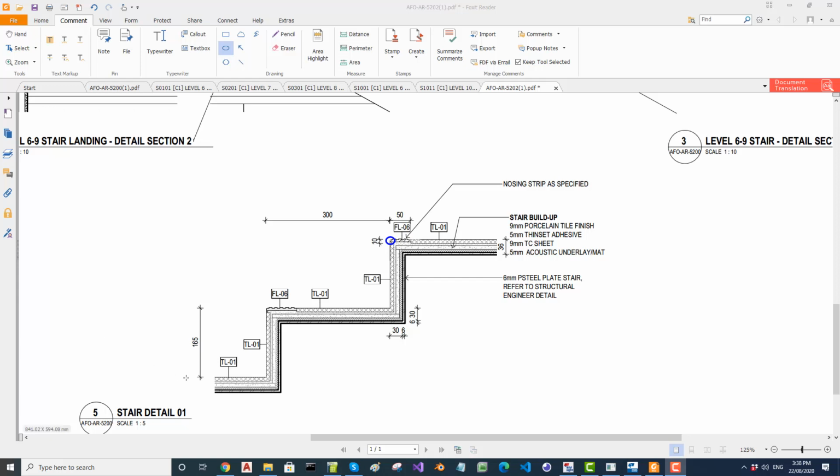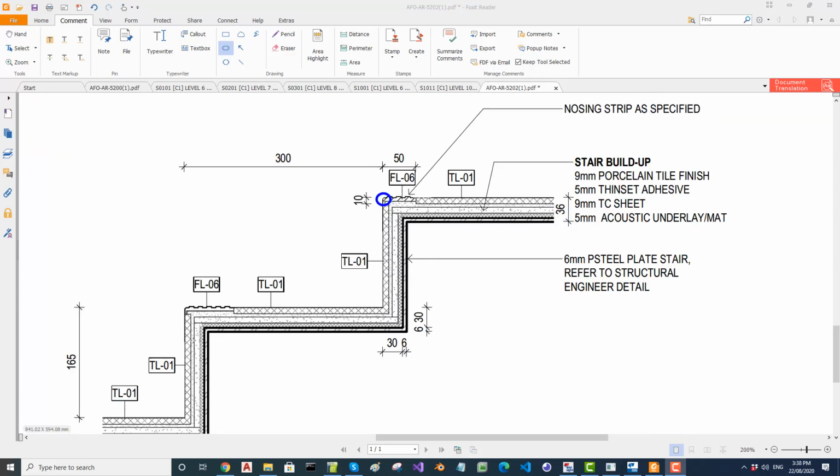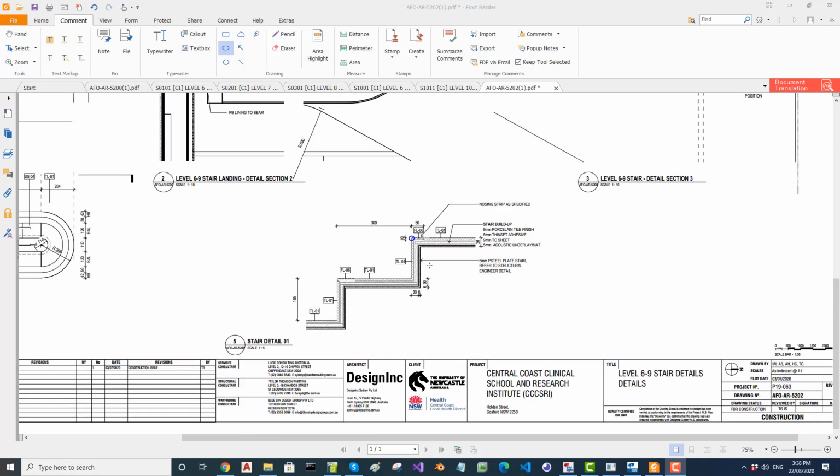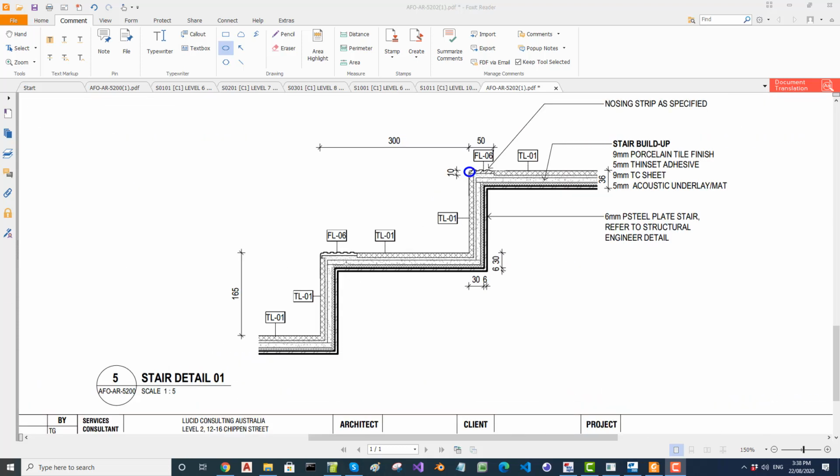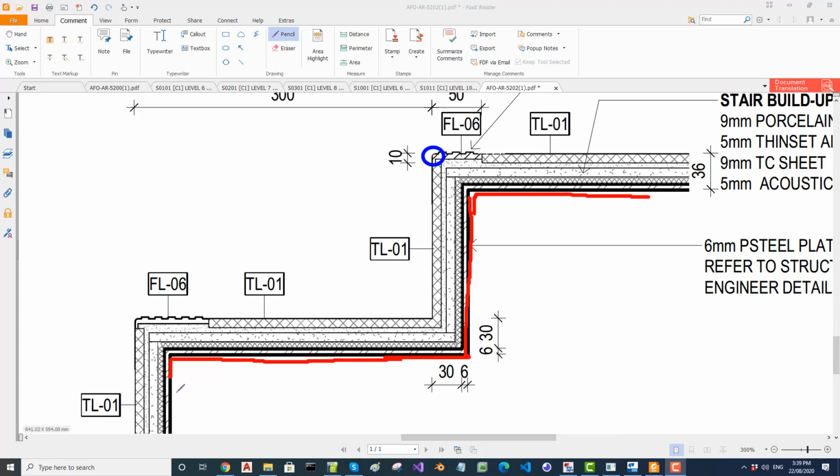The other thing to note here is the architect has shown these plates as sort of continuously folded, but that we can't do. It is not a good idea to do this. So you need to make this as individual tread plates. I will put a proposal for this type of construction, where you have this folding down, coming up and there, and then the next tread starts again.